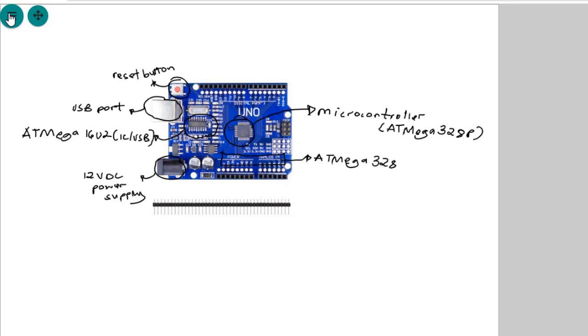Okay, this right here is a voltage regulator. A voltage regulator is used to regulate or control the spikes in voltage. So sometimes your voltage input might not be ideal, so the voltage could have some spikes, and the voltage regulator works to control the spike so that it doesn't damage your microcontroller. And the voltage regulator works hand in hand with these capacitors, which also help achieve the function of supplying steady power supply to your microcontroller.